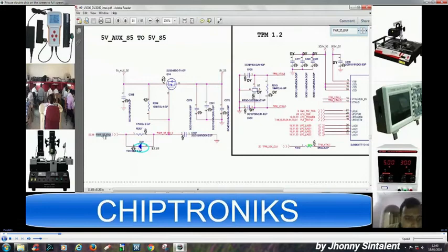And if this signal is coming, you can see this signal is ending with hash, and hash means if this signal becomes active, then the value 0 volt would be there, that is ground. So this ground is shifting over here, so the voltage at gate is 0, whereas the voltage at source is 5 volt. So VGS is less than a specified value.